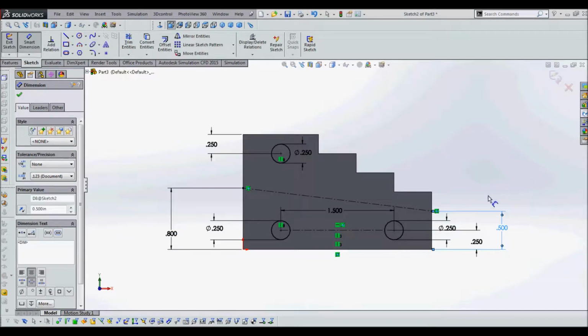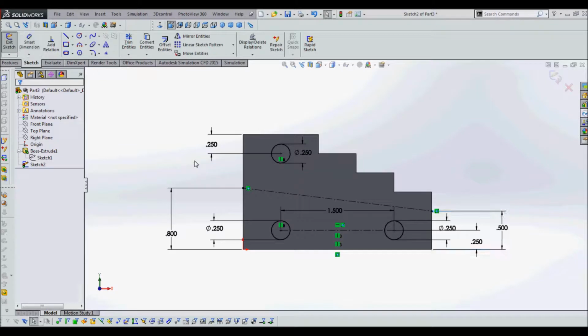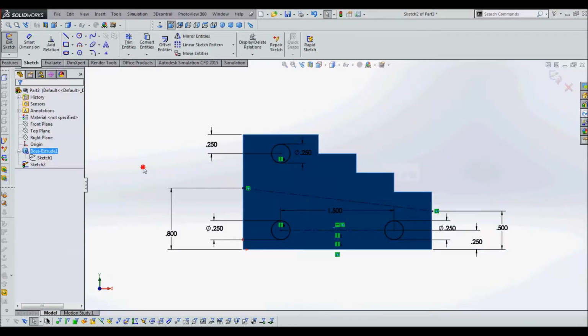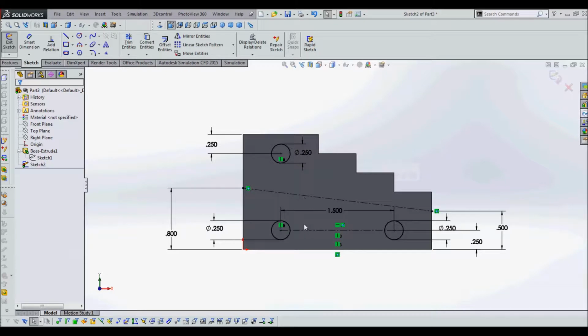Great, that looks good. So, as we said earlier, the construction line, we don't have to worry about either of these 2 construction lines extruding in this process because it's not going to interpret them as part of the shape. And if we do a quick check here, we'll see that all of our full lines are in closed loops, so SolidWorks should interpret that properly.